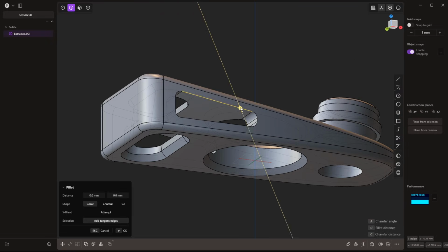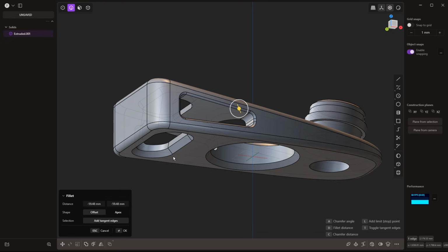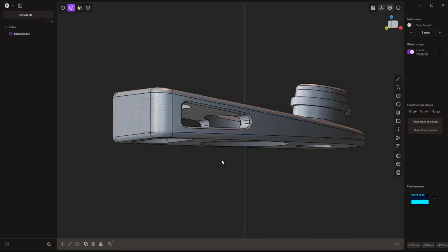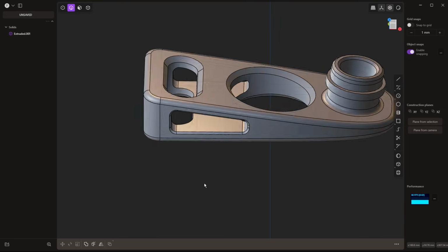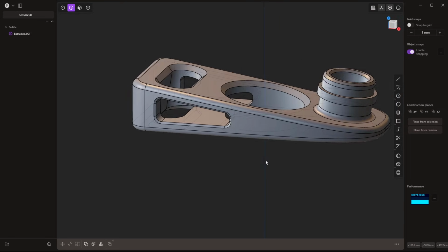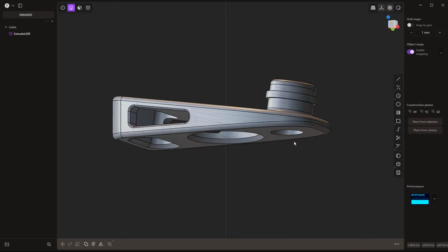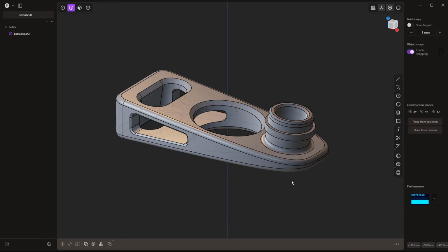Now that we've got this, we'll go to the outside edge and we'll add a chamfer, rotate it around, hold down Control, add a chamfer there. And you can see that we've now added that extra little detail. It cuts through both of those openings. And we did it relatively quick and simple by sketching from the side view and then just using some extensions or snaps to allow us to create something that was both parallel to the side faces and vertical or perpendicular to our ground plane. So those tools that we used and the general process for modeling is going to be pretty common across the board.